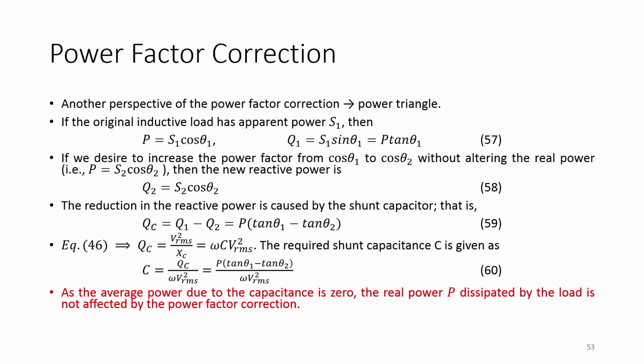First of all, for example, we are given this triangle. This is another method of looking at this power factor correction. From our previous knowledge of the power triangle, this axis is related to the real power, this is imaginary power, and because real and imaginary parts are 90° apart, this is 90° of angle, and the vectorial summation of these two vectors is S, the complex power.